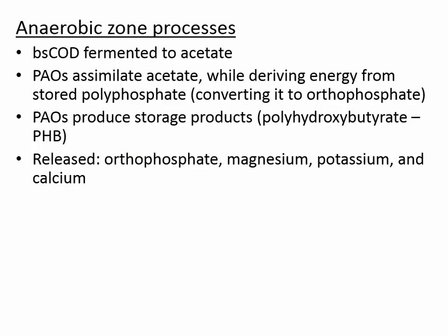BSCOD, that means biologically soluble carbonaceous oxygen demand. That's fermented to acetate, and the PAOs are actually consuming acetate inside of the anaerobic zone, and then they're also using up their stored polyphosphate. And so remember, which one is polyphosphate? Is that the one that is soluble or insoluble? Insoluble, right.